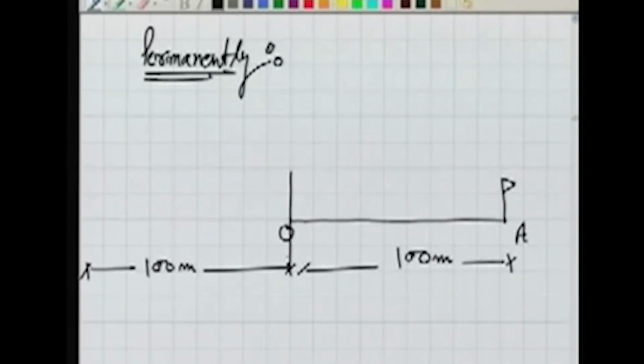So the situation in that case is, if I bisect A, then I transit it back. That's transiting. Earlier I am bisecting A, so I am seeing through the eyepiece. Now A is bisected. Then I transit it.